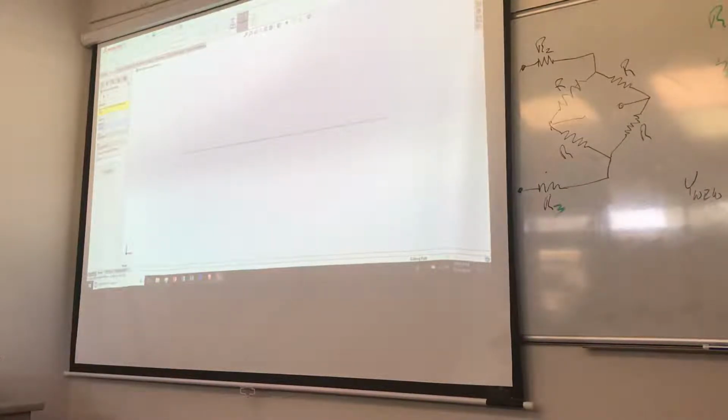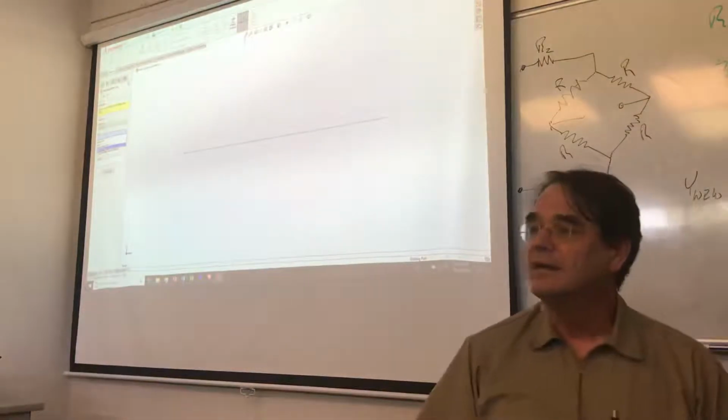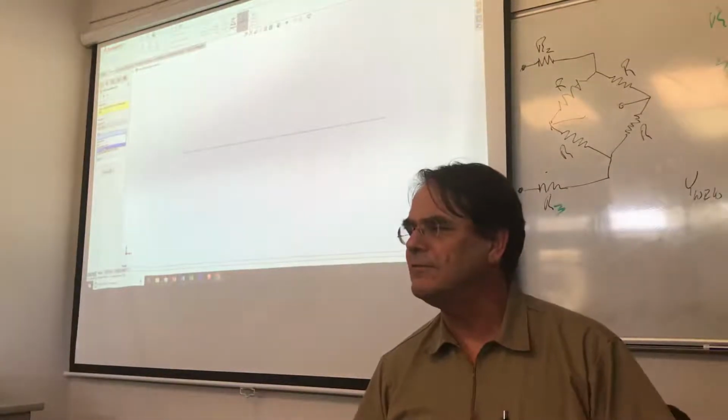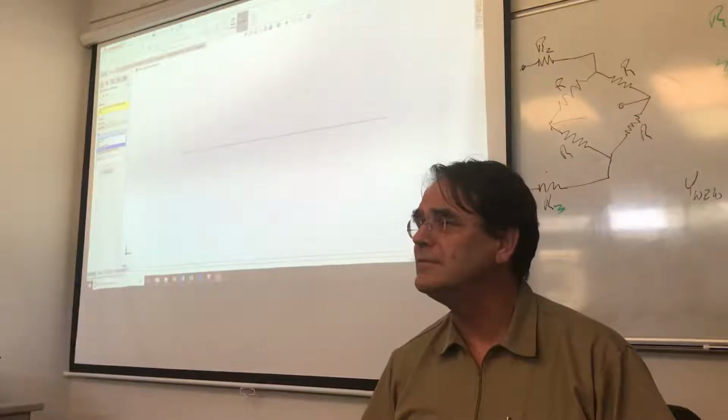Okay, now when you come up, yours is going to look different than mine. Yours is going to have something that says ANSI inch or ISO, right? And if you click on ANSI inch, which is the only one here, you're going to click underneath it, you're going to see some things that look like this, where it says angle iron and pipe and rectangular tubing and square tubing, and it'll also say C sections and S sections and a few others in there, if I recall, right?